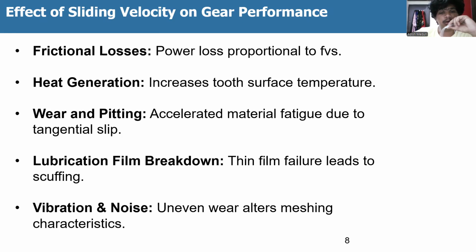Lubrication film breakdown: thin film failure leads to scuffing. Vibration and noise: uneven wear alters meshing characteristics. So those are the effects. We'll go to the next slide.